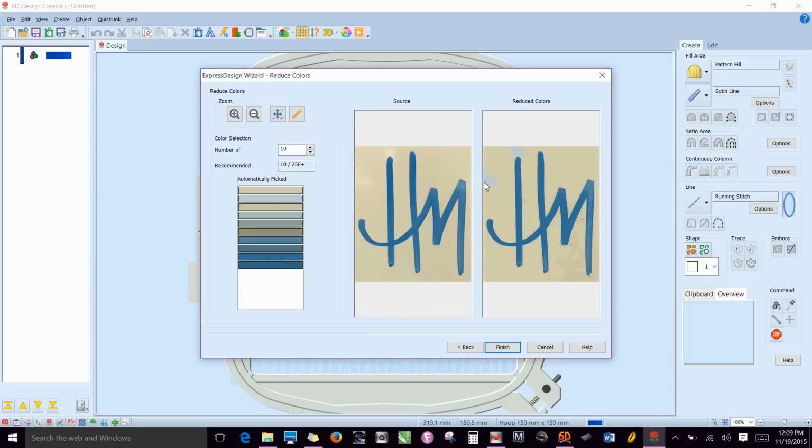Now, if you were auto-digitizing, you want to make sure that you get these colors to be pretty close so that it shows right. You don't want little blue-gray areas here, things like that. If you were doing the background, like you can see here where it kind of interpreted this as a darker beige. It's interpreting these lines, because it's marker, it's an inconsistent color, so it's interpreting these as multiple shades of this bluish color.